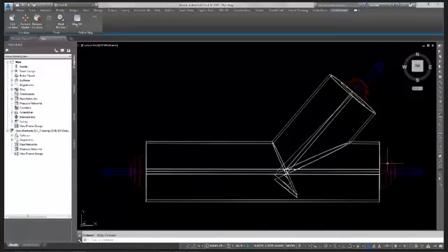The first connection point you put in is where that part will connect when you insert it into your pressure pipe networks. So in my case, anytime I bring this part in, it's always going to connect on this side of the part. When I built it up, I added all my connection points because this gives me the ability to now connect to 3 different outlets on there. I need to publish my part.